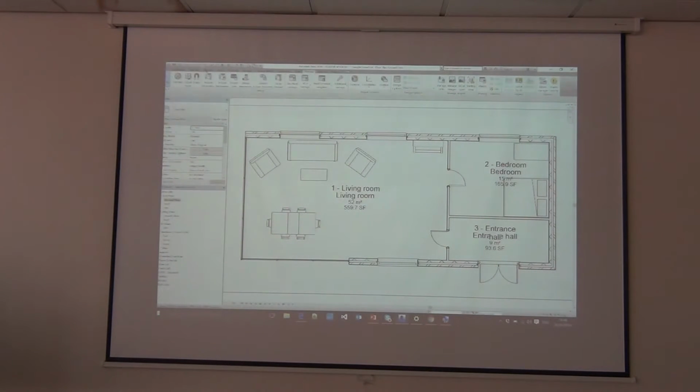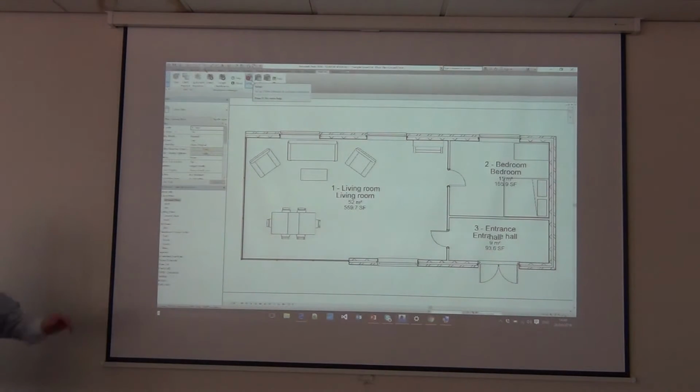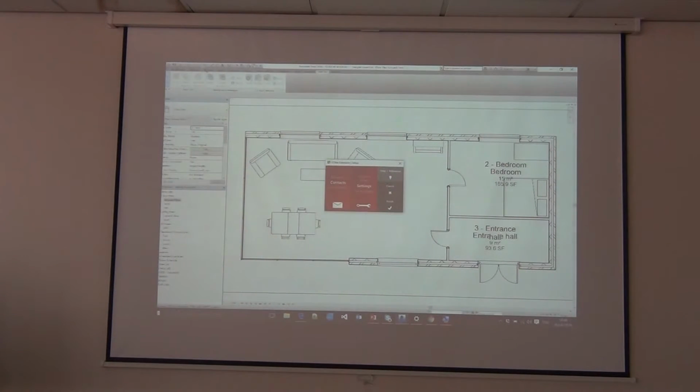So I'm going to show you what that does. I've downloaded that plugin. The documents in there show you where it is, and I get these three things now for doing COBie. So I've been talking about IFC. This is now the native Revit way of doing COBie, okay? Which looks great. So I go in here and set up my contacts, all my settings, and away I go.